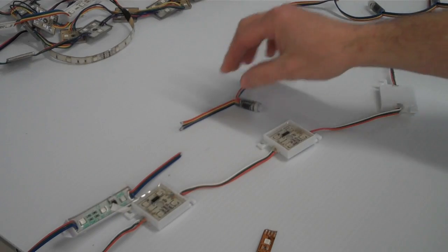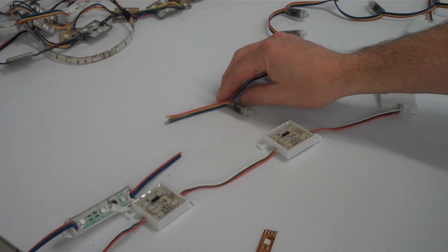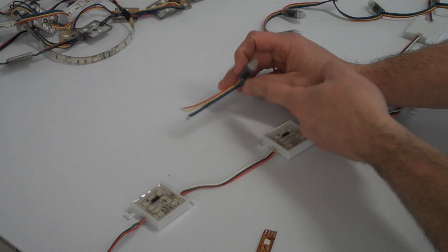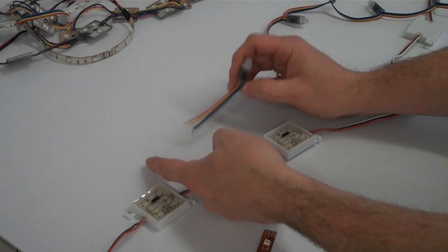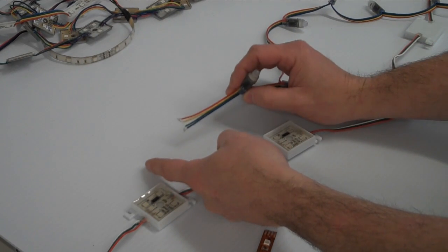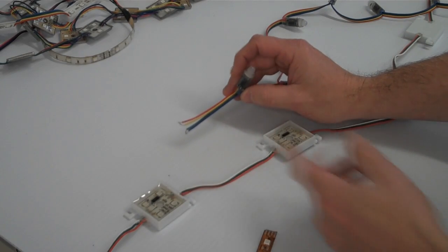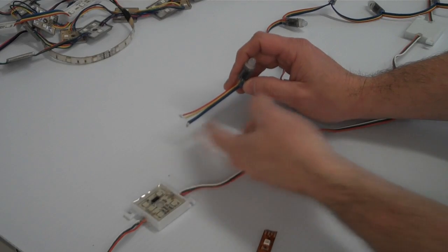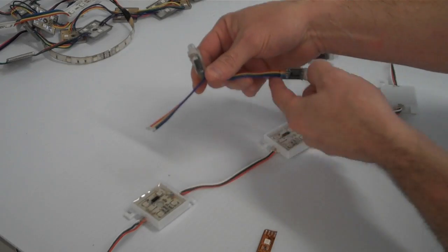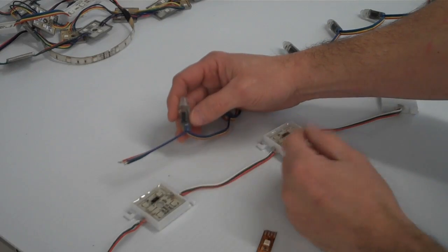Now, some other unique things that you may have within a particular controller is dead node or repeating node skipping. What this allows is if you have a long distance between your controller and its output and the first pixel, you may have such a distance, such as 20 or 30 or 40 feet, that you need it to be able to reproduce the signal. As I mentioned, each one of these pixels reproduces a signal, and they can only go a certain distance, and that varies based upon the particular kinds of chip and wire and a variety of other factors.